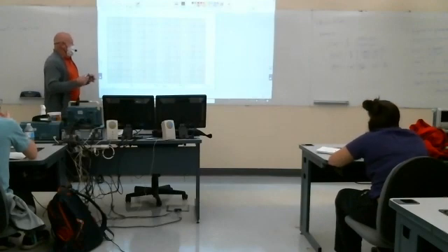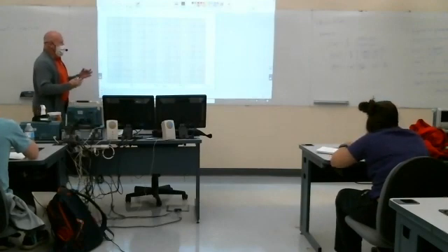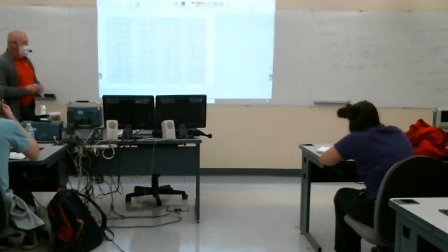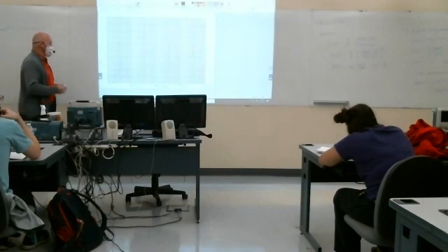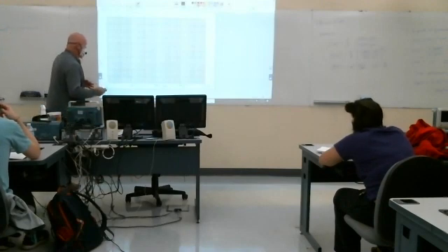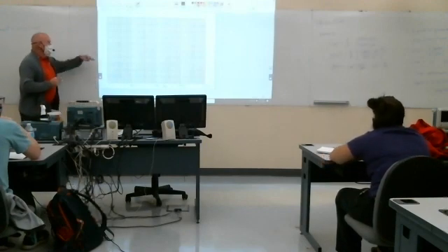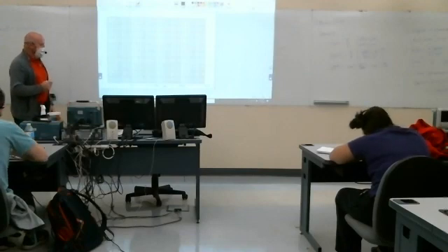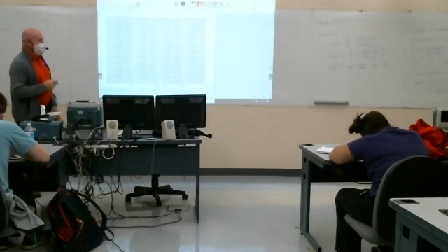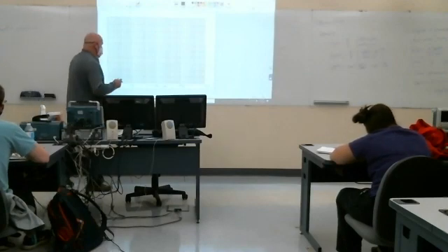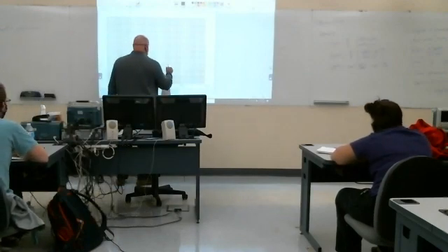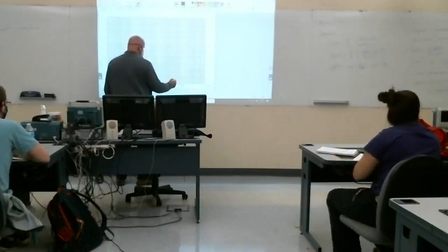Okay. Now, the other thing that you have to do is lay out the vertical scale. Sometimes you end up making some erasures here, trying to guess. So I'm going to label that line 0. Could be any one of these bold lines. But now I'm going to mark my critical frequencies. The 8,000 is in the numerator. I'm going to mark that on my 0 dB line.